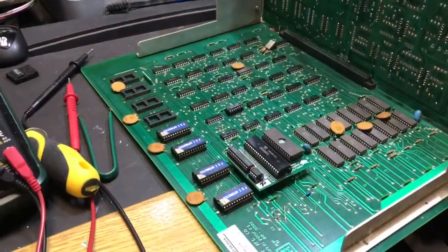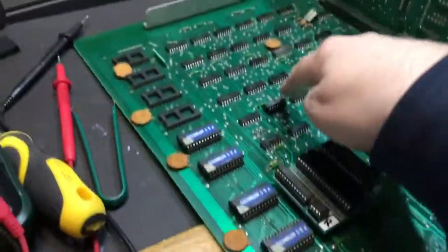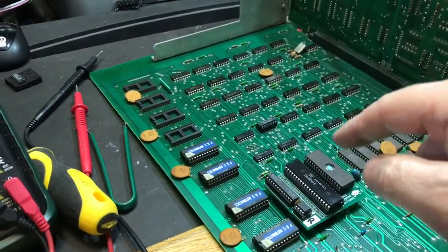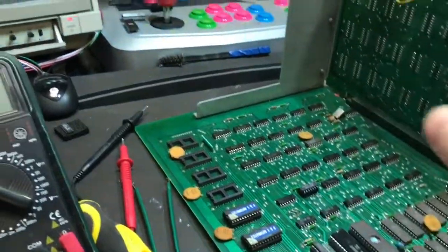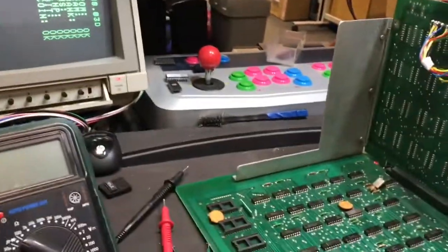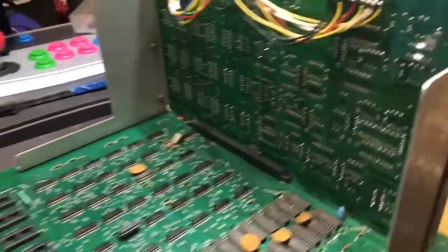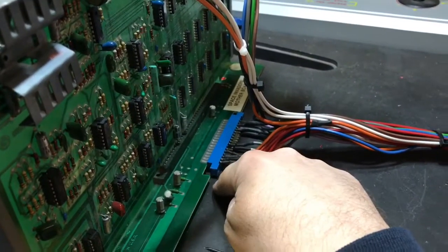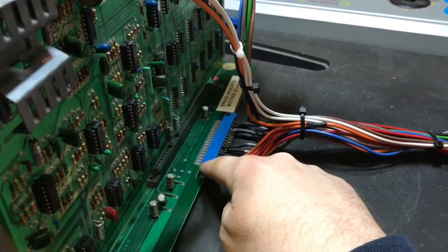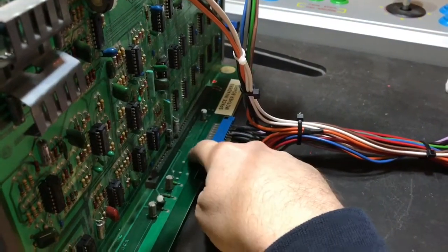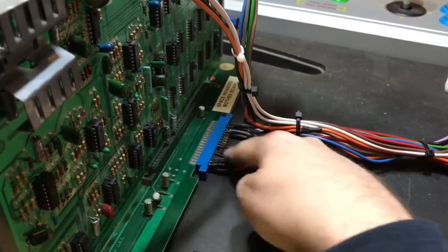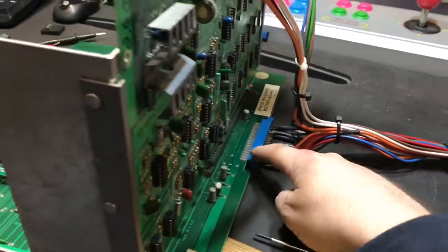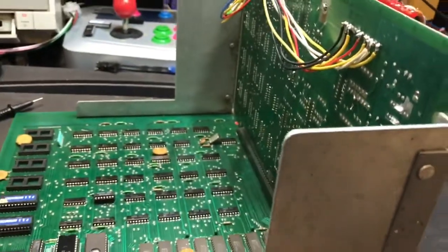I had a little bit of a scare for whatever reason after I changed the 7474 chip out. For some reason the board would not come up with a full decent picture again. So anyway, I fixed that. It was really weird. It turned out to be my edge connector here, not the board. The keying and the size of this connector are just a fraction off from one another, so it's easy to get the pins very slightly misaligned, and that was causing the 5 volts to trip out and just partially ground out.